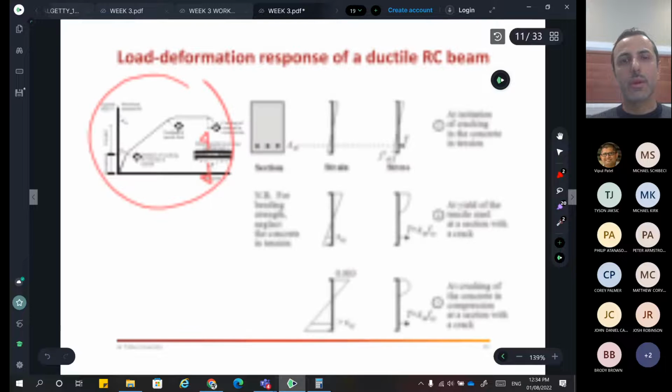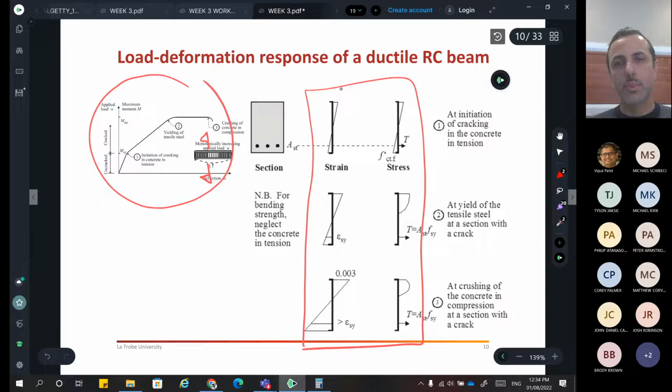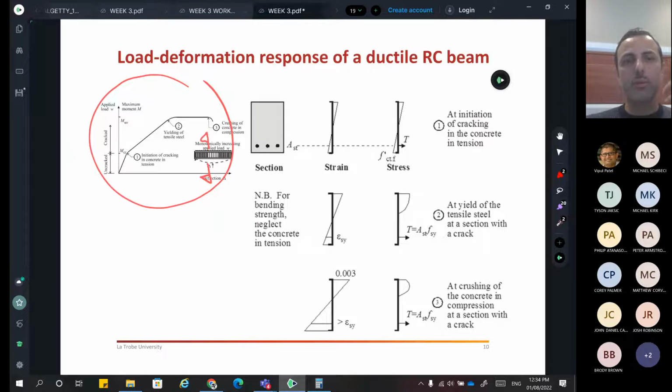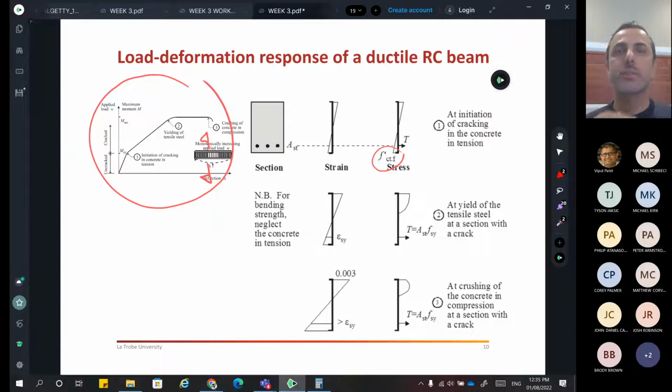And if I go back to where I was, so back to this one, you had here as the first column the strain, the second column represents stress, and here we're just going to focus on the 3 phases. All right, just again to build a correct understanding of those milestones I mentioned. So what's really happening with phase number 1? It is the point where, as we said, the concrete will reach its maximum tensile capacity to take shear.